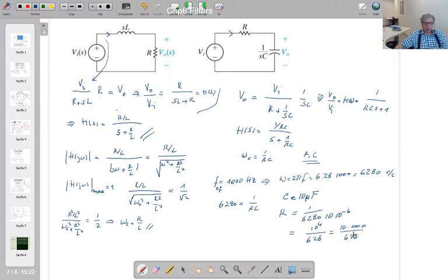So what we have done, the simplest way of explanation for that: we have chosen the capacitor value, the cheapest capacitor value, and found out the resistor value. If the resistor value is very low, not very common, let's say 1 ohm, then you increase your capacitor value and get a reasonable resistor value.